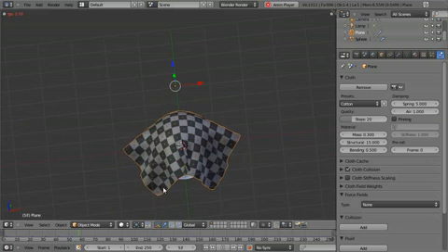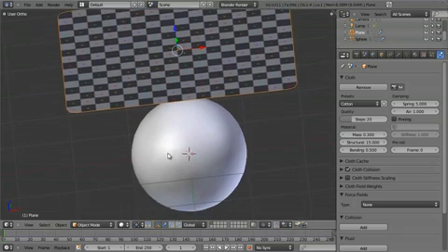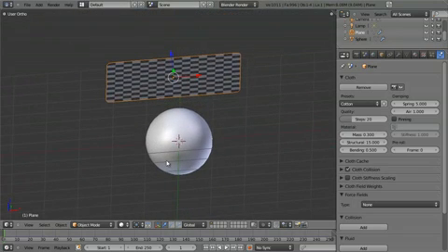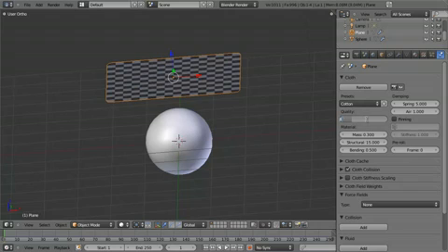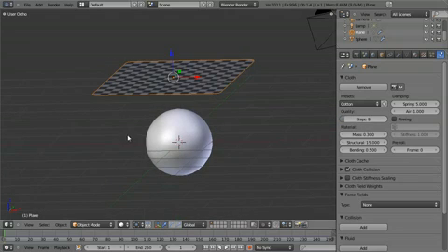So you may not notice a lot here, but with the more complicated your mesh gets, and particularly as you get more and more moving objects or moving collision objects, the higher the quality, the better it'll be. But it does come with the downside that it kills your simulation time. So we're just going to go ahead and turn this down to 8, so just slightly higher than the default.